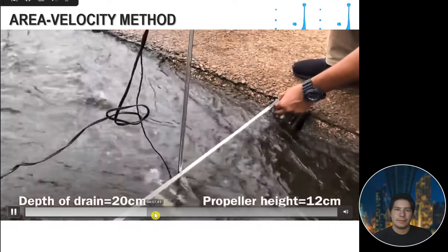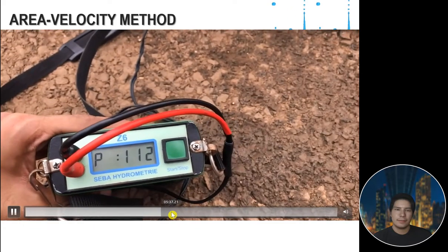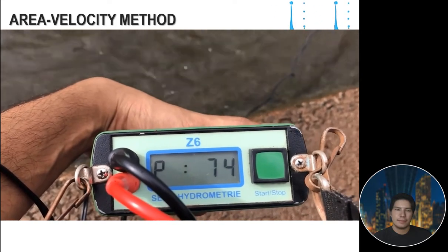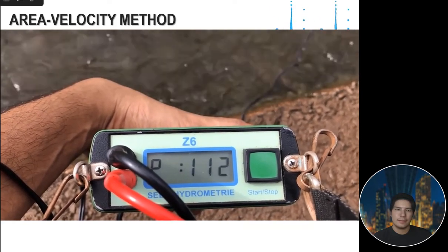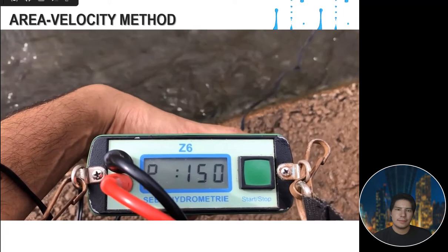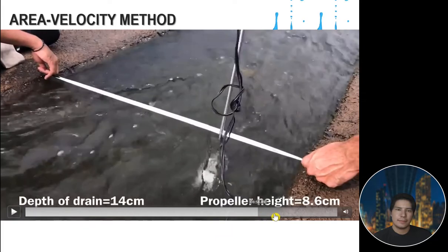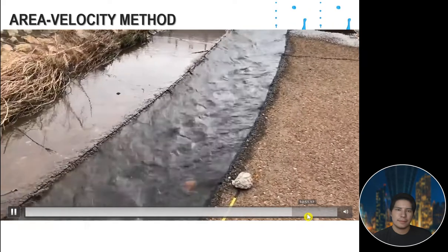The second reading we will be taking at 50 centimeters, where the depth was 20 centimeters to 25. We got 163 rotations in 30 seconds. We measure the depth again in 30 seconds, which the surface floater takes.